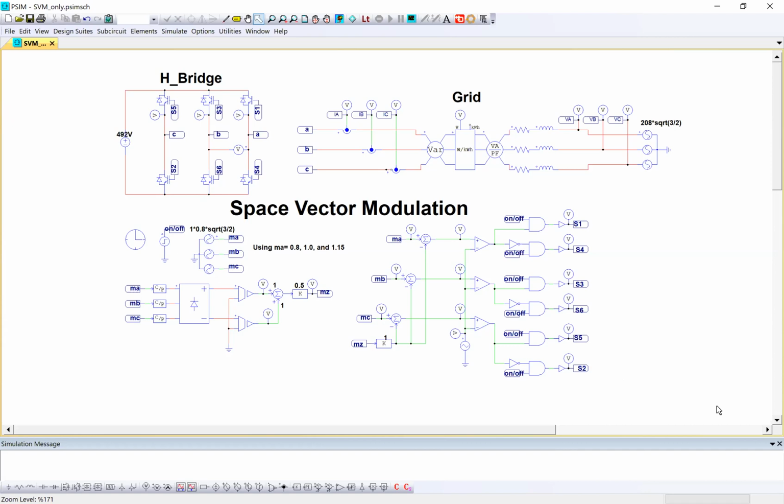So this is still in process, but this gives you an idea of what you do in some of the power engineering courses, specifically working on control systems, working on AC to DC converters, which this H bridge is basically. And then you have this resistor and inductor, the resistor to model the losses in the system, the inductor to act as a current filter.